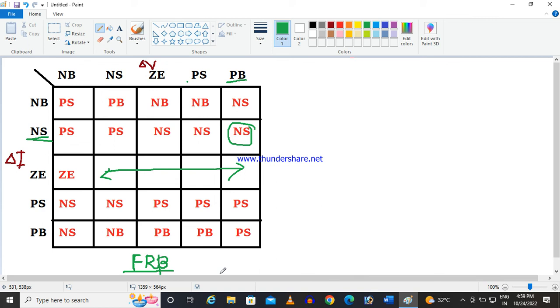Okay, so this fuzzy system has 2 inputs and 1 output, those are the fuzzy variables, and each fuzzy variable has 5 membership functions: negative big, negative small, 0, positive small and positive big. Then how these 3 variables, the 2 inputs and the output, are connected, at what rule they are interlinked. For that, this is the fuzzy rule base.